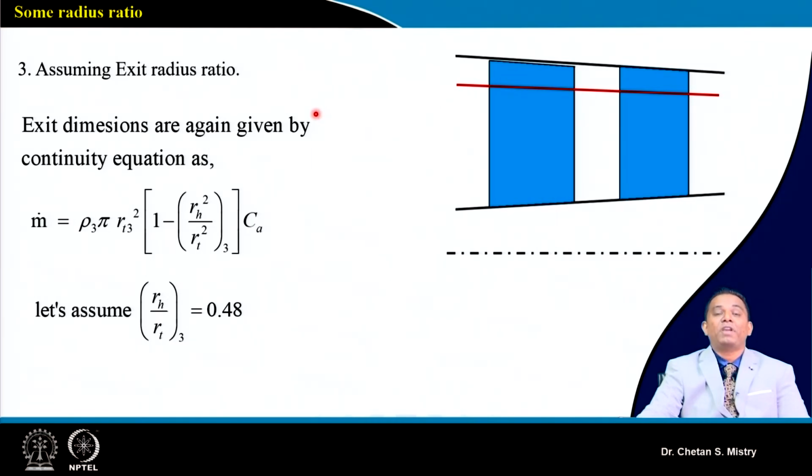There will be a connection between the LP compressor and the HP compressor through the intercompressor duct. Aerodynamically, this intercompressor duct needs to work absolutely fine with minimum losses and flow distortion. And it may be possible that the aerodynamicist doing that design goes aggressively and says my entry, or the exit of the LP compressor, will have this dimension.